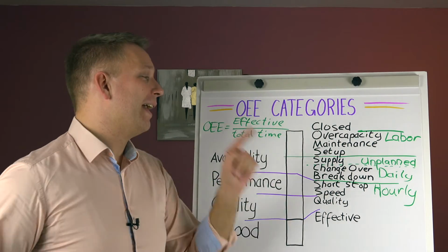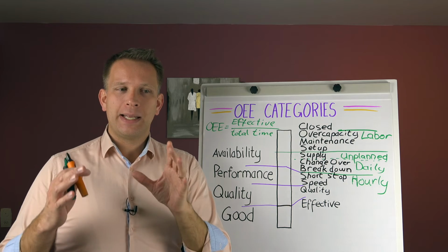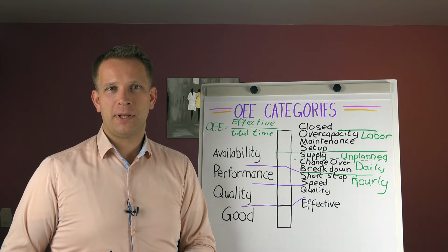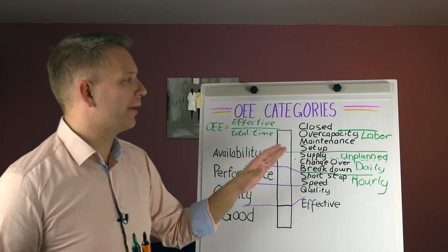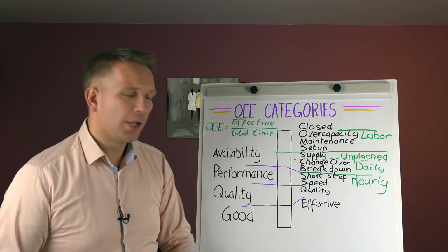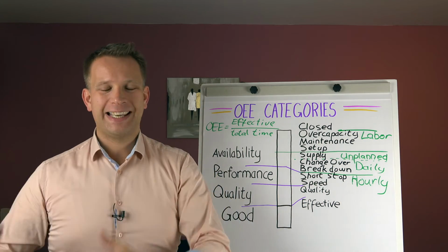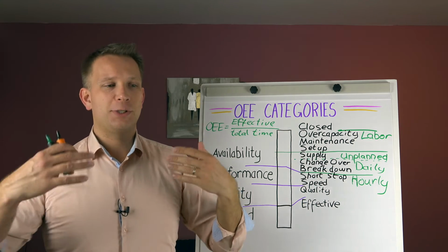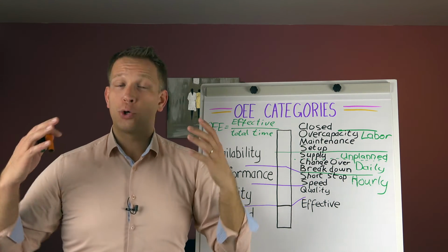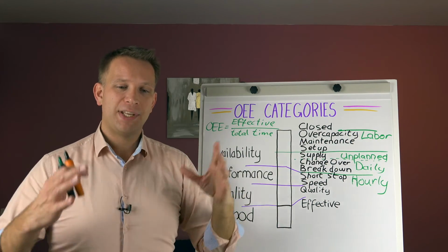Very deep discussion. The main thing is, do you see how these categories shape the way we report or use OEE numbers? And there is not per se one right way for this. But these categories are made so that you can shift your equipment effectiveness calculations, loss analyses, and predictions to different levels in the organization. You can imagine that on a corporate scale, everything is important because we are, for instance, talking about investing in new big lines.